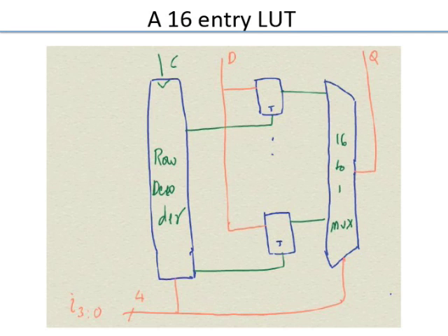So now the question is, can the write be done serially? Of course you can do it serially also. You can only write one memory entry at a time, whether it's a random access memory or a serial one. When you say serial versus random access, that's not what we are saying. If I want to write, for example, the 16th entry versus the first entry, how many cycles does it take? In a random access memory, it is the same time whether I write the 16th entry or the first entry. Whereas in a serial memory, you shift serially.